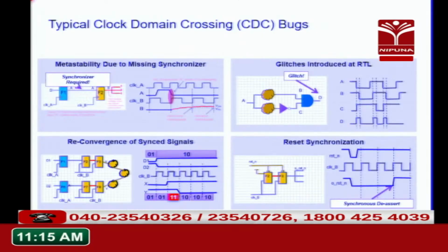Similarly, like clock, you can do reset synchronization as well. Reset is when you say a certain block is reset. Whenever we switch on your mobile phone, let us say, if there is no reset, your display could be doing something, your memory could be doing something, your 5G network may not be on or 4G network may not be on. Different blocks of your design will be at different states.